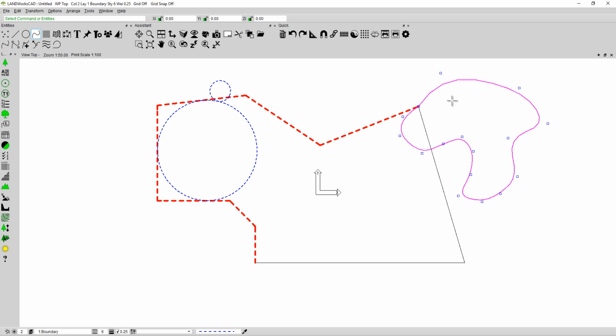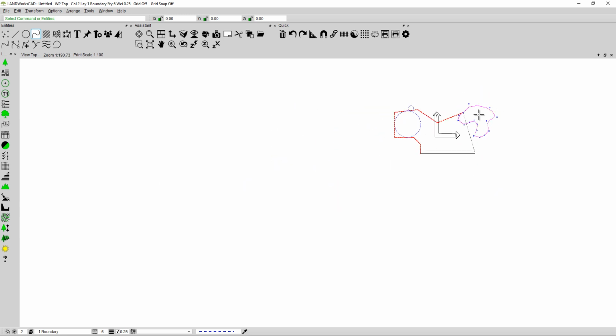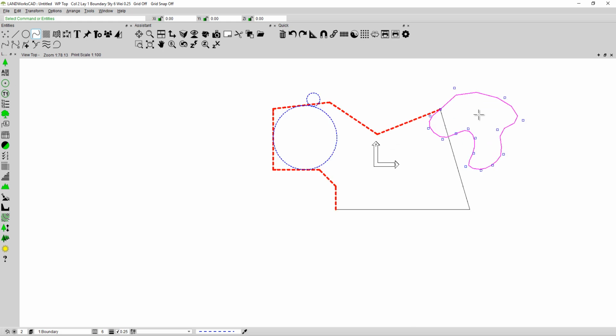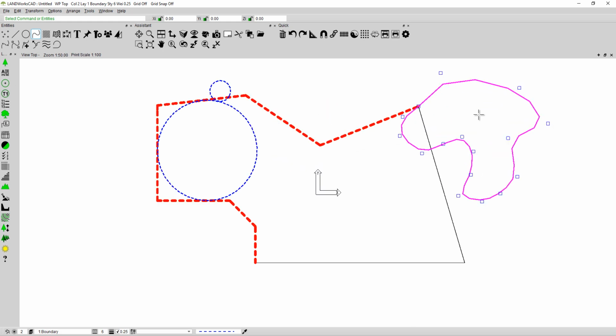Now a curve can be as smooth or as bumpy as you desire it to be, and you'll notice that I haven't yet zoomed in or out on this drawing. It's very easy to zoom, and it's something that you'll want to do a lot. So here is what you do. Hold your cursor in the area that you wish to zoom, and then roll your mouse either away from you or closer to you to bring the drawing further away or closer to you.